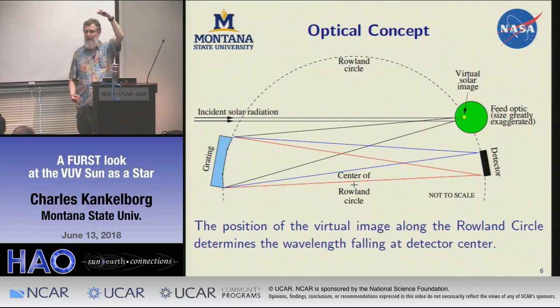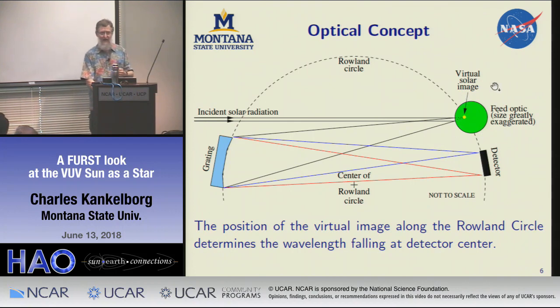But it gets you the whole sun. It's important, though, that this virtual slit, or this virtual solar image, be quite narrow. And so we have sized our cylinder so that it makes a 15 micron image of the sun. That requires a 6 millimeter diameter rod here.